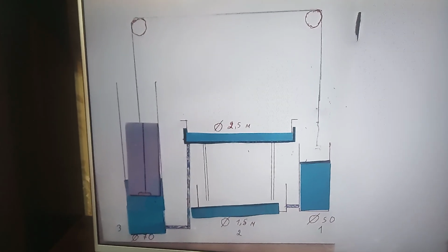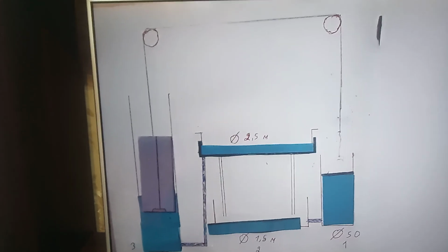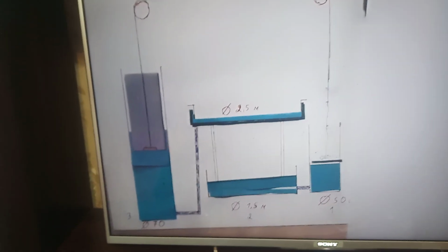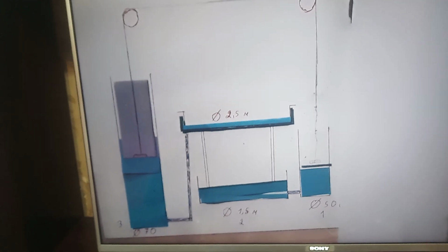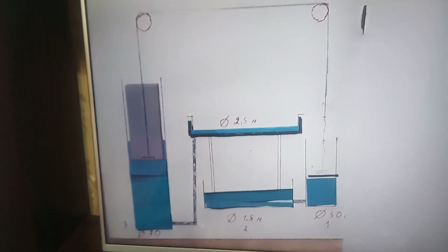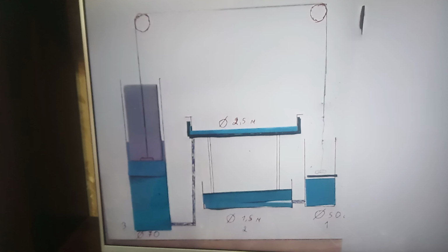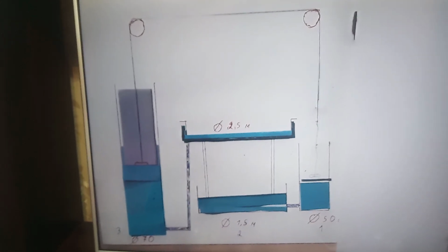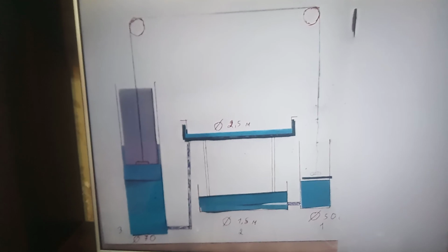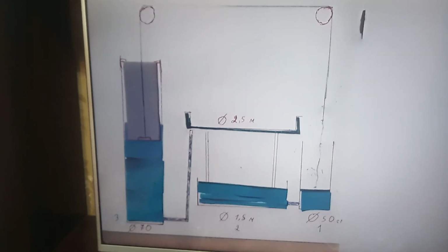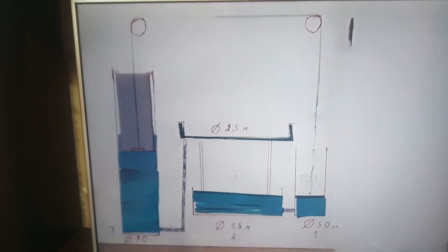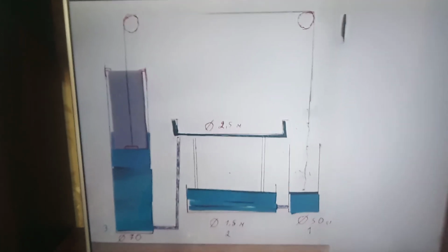When the float goes down a meter, it will return the piston to its original upper position, and the piston of the second cylinder to its original lower position, and the liquid from the third cylinder will return to the reservoir by vacuum. When the piston of the first cylinder reaches the upper position, the engagement device will rest against the limiter and will be unhooked, which will lead to the return of the device to its original position.